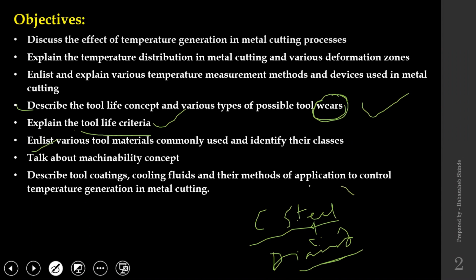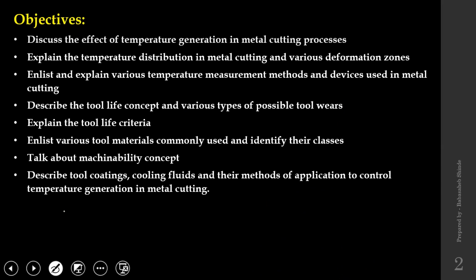So out of all these materials, when it comes to selection of the particular material, we need to consider certain conditions. Which material you are machining, at what machining speed you are machining, what type of surfaces are desirable, what type of accuracy is desirable, and depending upon all those things we need to consider the tool material, right?